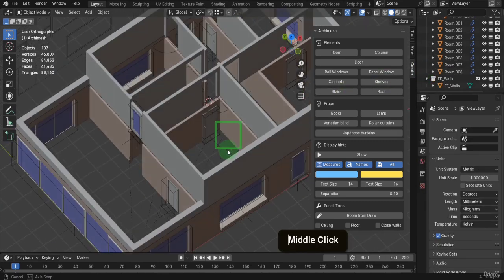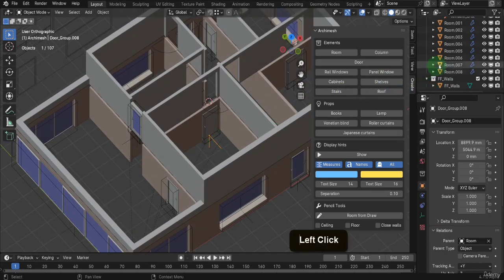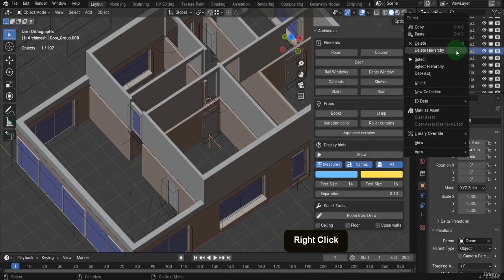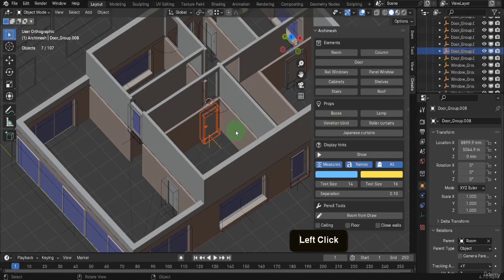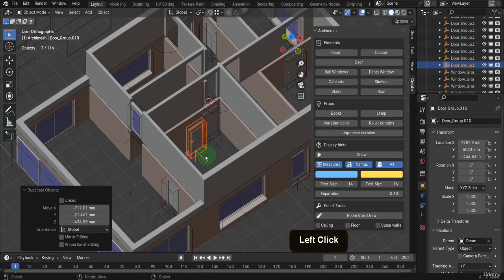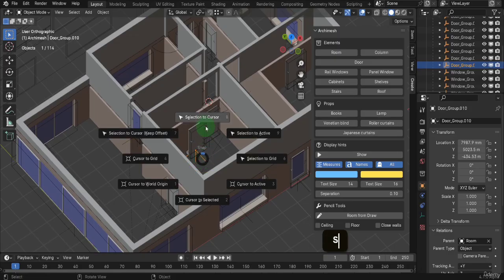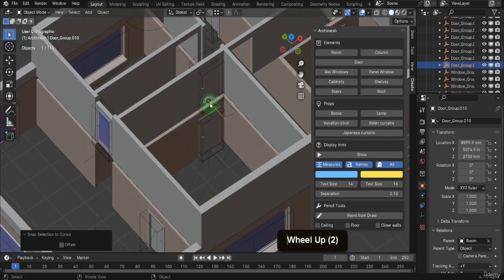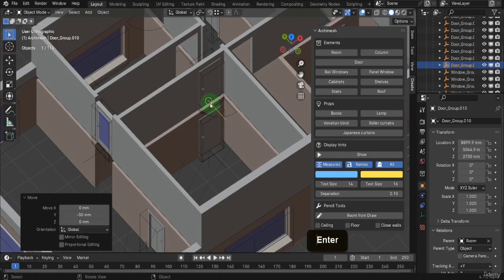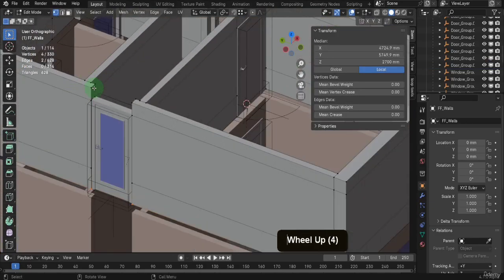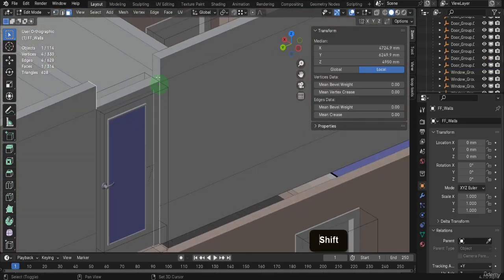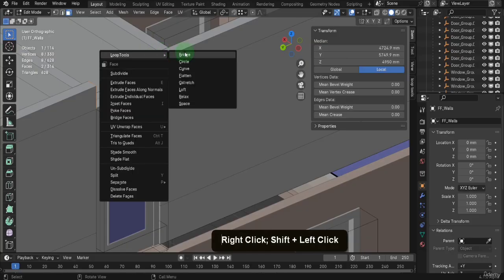From the ground floor, we can select a door empty. Now select Hierarchy. Press Shift plus D and drag away. Select the empty. Press Shift plus S and put selection to cursor. Try work around and add in the remaining doors for the first floor. I will also get these added between videos.